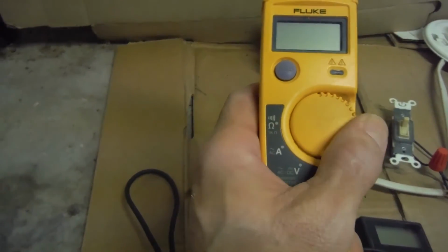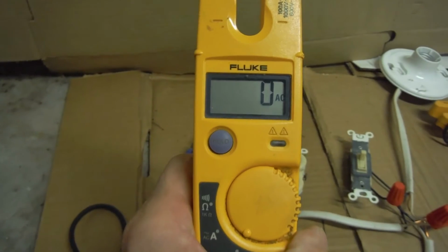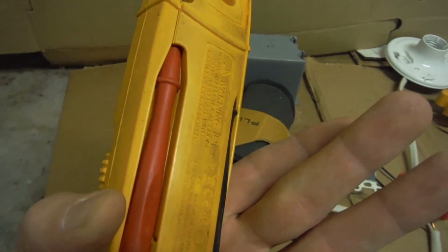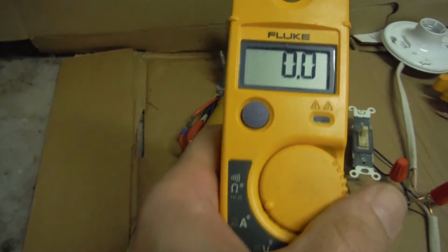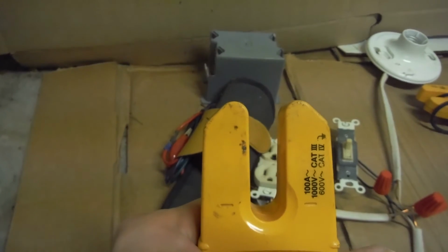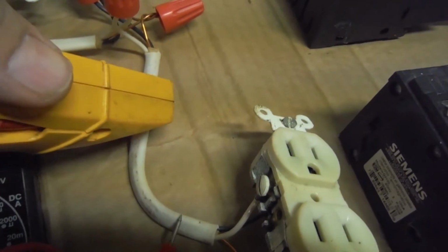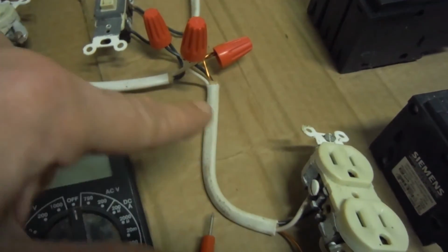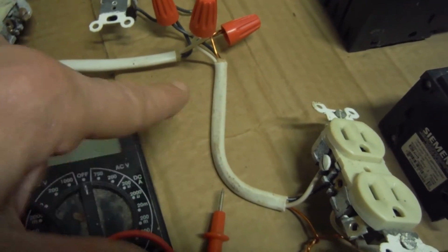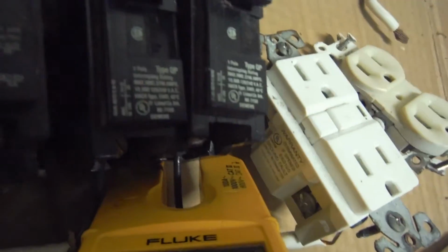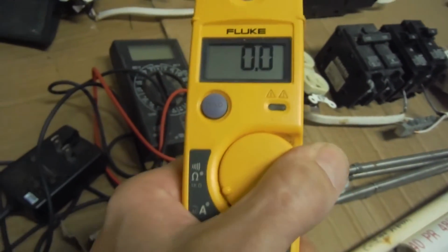As you can see right there, the first click is volt, defaults to AC. You connect it to DC, it's gonna measure it. And you use your probes right here on the back, and bam. Amperage, it automatically defaults. You use your little dealie right here. This you cannot just put around a wire and measure it. Why? Because you got your hot and your neutral going through there. They neutral each other out, and you'll get a 0 rating. So what you've got to do is come down here and actually go around one of the wires. Right here, I'm going around the hot wire. But it doesn't matter. Just go around one of the wires. You can actually measure it in amps and ohms.